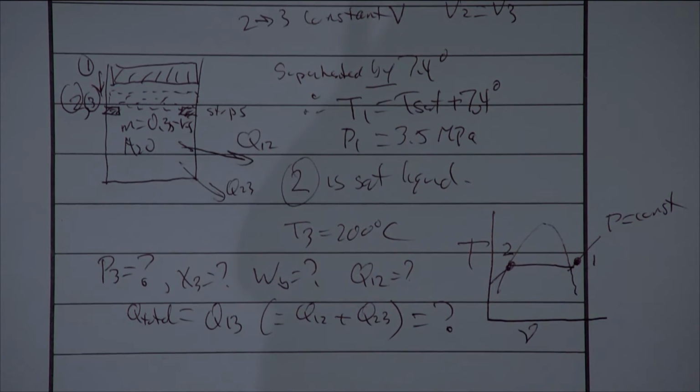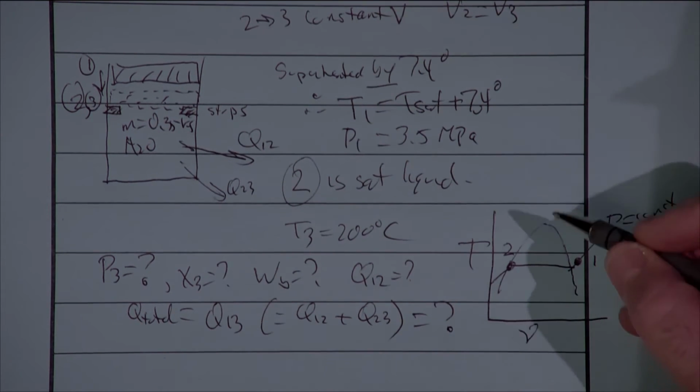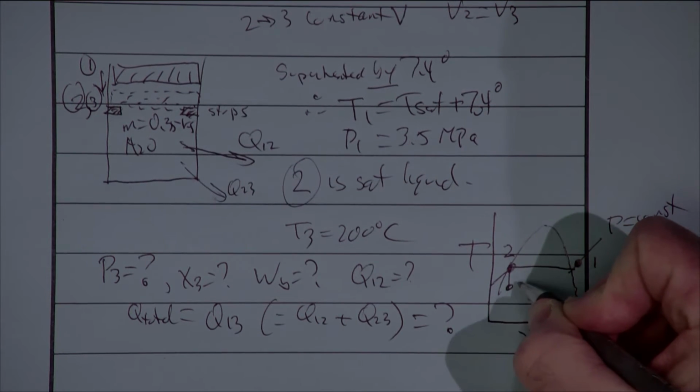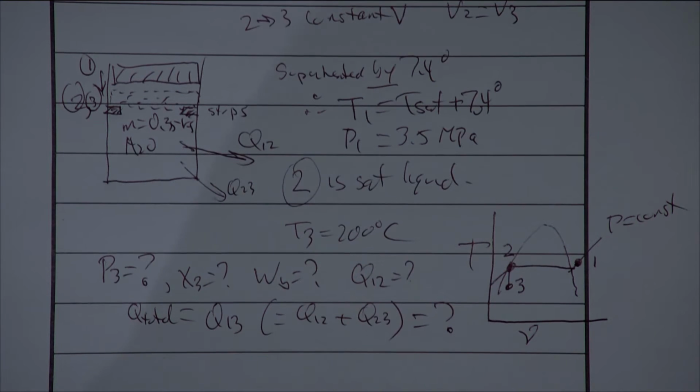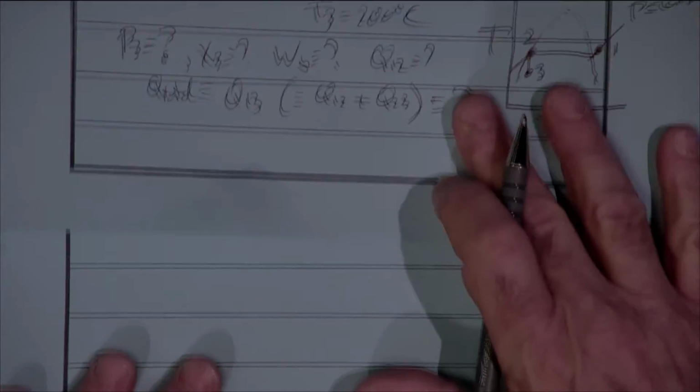And then we have a constant volume process, right? Now, note it's a closed system. The volume's constant, the mass is constant, the specific volume is therefore constant. And because we're cooling, the temperature is going to drop, and we'll end up with state point 3. That's right there, directly below state point 2. So here's our initial setup. Not really quite done with the setup, mostly done with the setup.